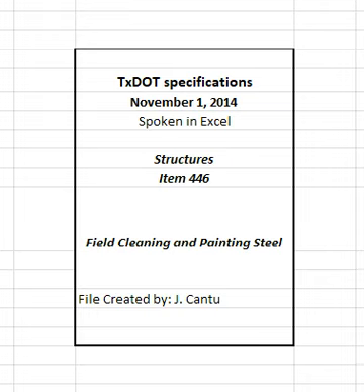2.1.5 System 1-2B. Provide paint in accordance with DMS 8101, structural steel paints performance. Provide inorganic zinc, IOZ, prime coat, epoxy intermediate, and urethane appearance coat. Provide epoxy zinc prime coat, as recommended by the IOZ manufacturer, for touch-up of IOZ.